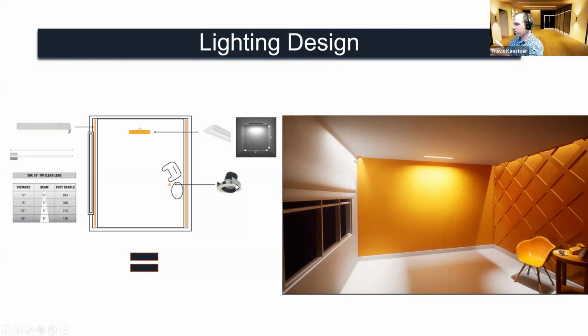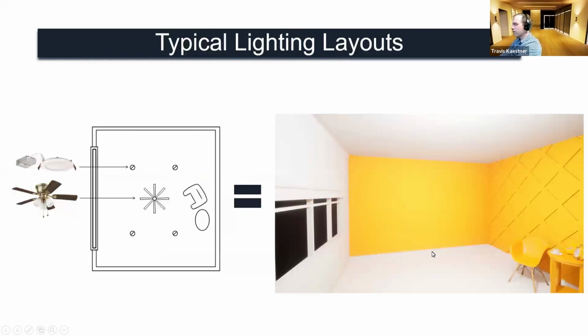Another way to do it is fixtures that have recessed, adjustable optics, used to highlight this chair right here, and it's creating intentional contrast. It draws that out. You get a recessed linear wall wash here that can highlight your branding for your commercial space or your art for your residential unit. And you have the two linear light bars shining out. It creates a very different feel than this. There's time to use both of those, and a lot of it is owner preference too.